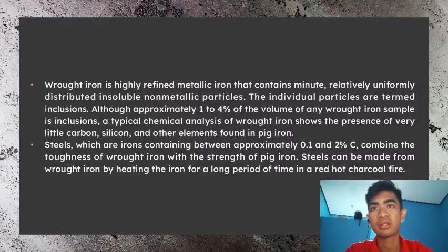However, pig iron can be cast. In fact, the carbon level of pig iron approaches the eutectic composition of 4.30% carbon in the iron-carbon system. In the iron-carbon system, this eutectic composition results in a melting point of 1140 degrees Celsius. This is much lower than the melting point of pure iron.